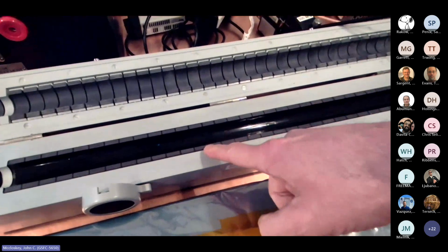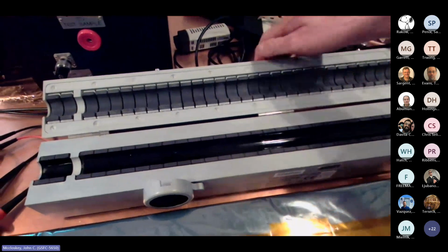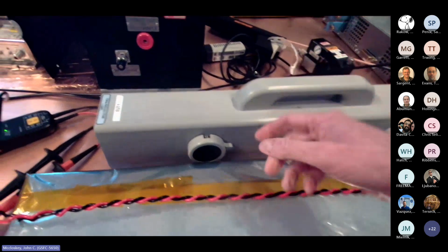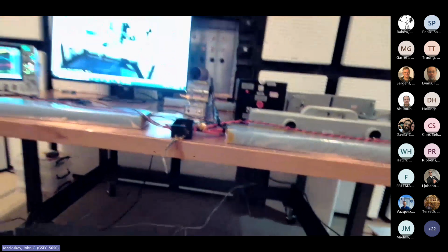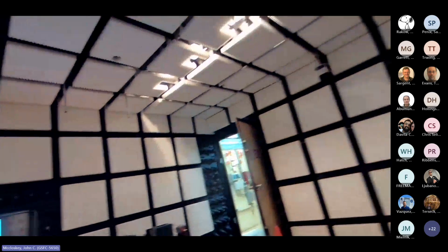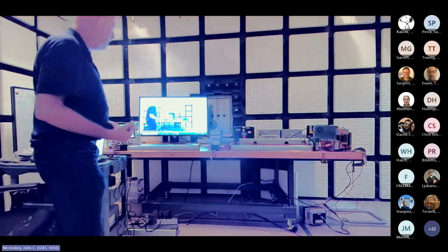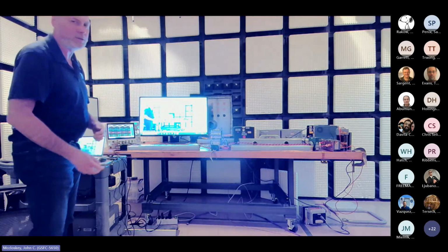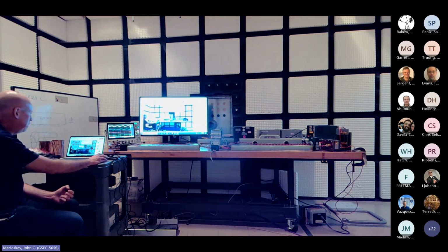Do you think the relative permeability of this is 1? Probably not. It's a magnetic material, so that mu sub r is going to be something greater than 1. Whenever your relative permeability or relative permittivity, which is the dielectric constant, is something greater than 1, that is going to decrease your speed of propagation, right? You can't be faster than the speed of light. At least I don't think we figured that one out yet. But it's going to be smaller. It's going to be lower than the speed of light.